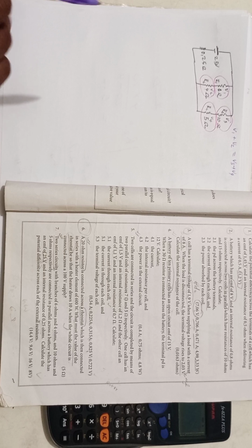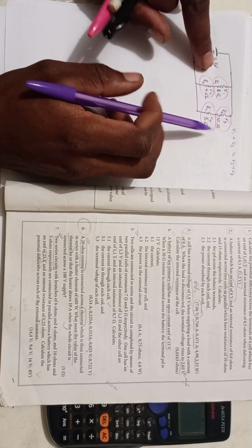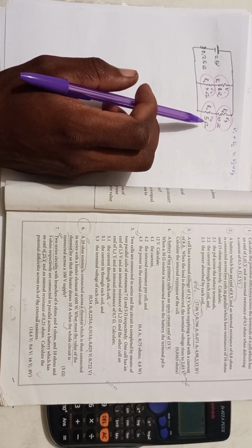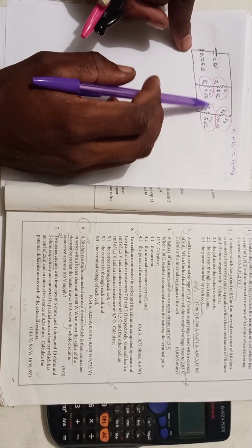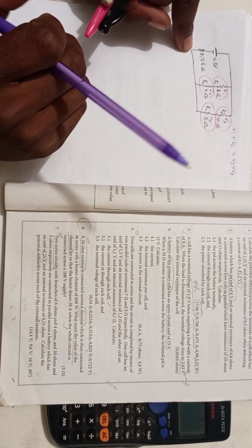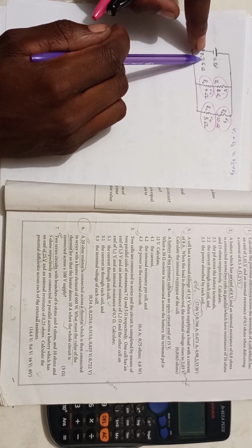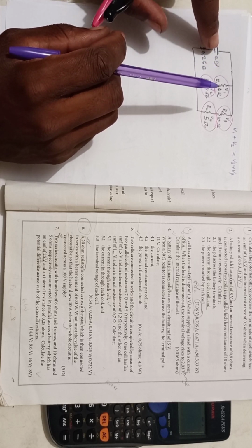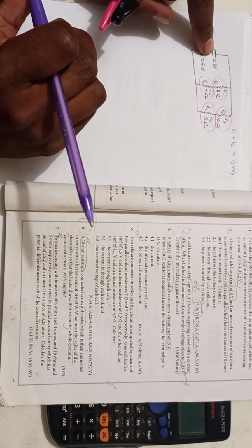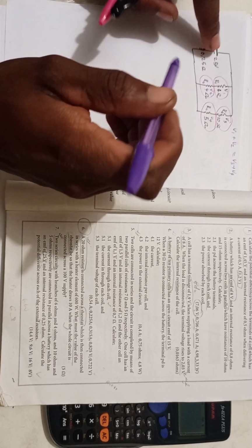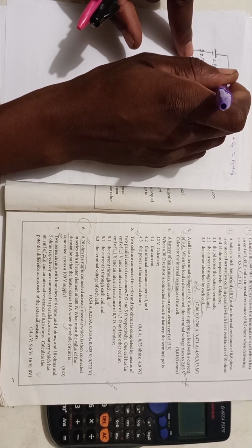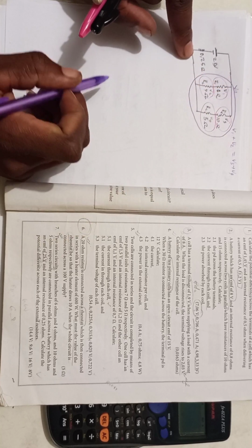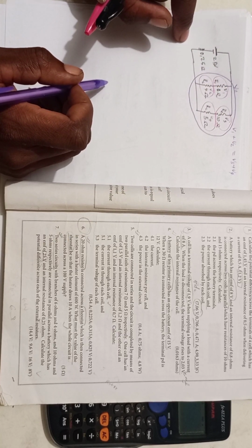Okay, where do we start on calculating V1, V2, V3, V4? If we can calculate the total resistance of the circuit, where will that help us? It will help us get the total current. Getting the total current can help us determine the volt drop across here, or V parallel, the potential difference of the circuit.